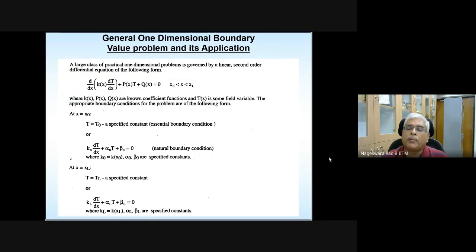But for some problems, the strain variation may not be constant. In such cases, or if you want to capture strain more accurately, you need to go for higher order elements. Instead of a two-node element, we need to go for a three-node or four-node element.